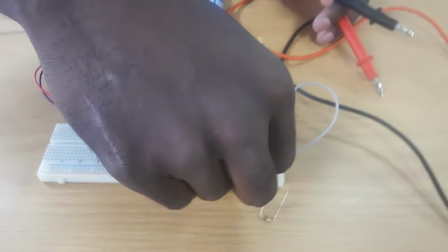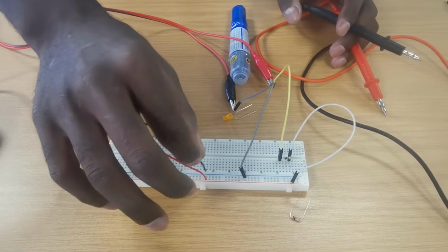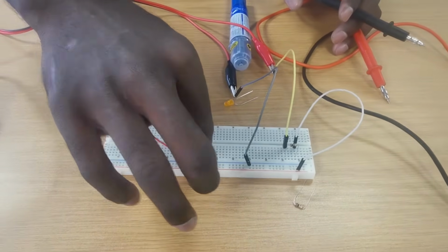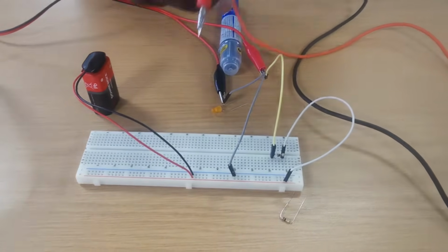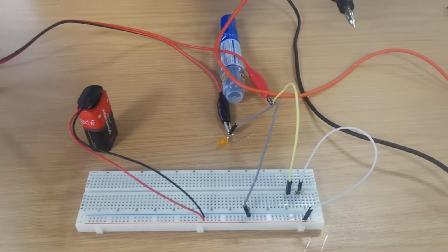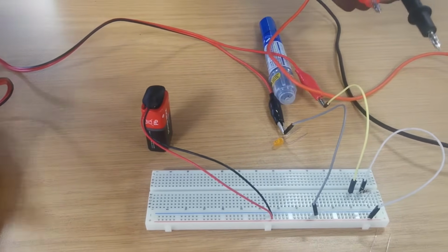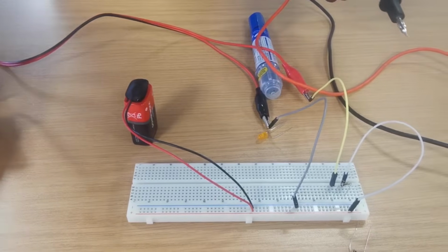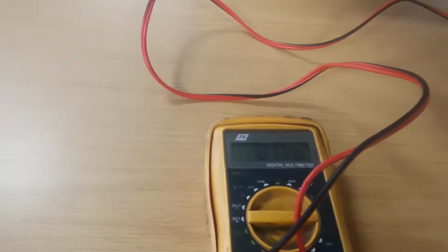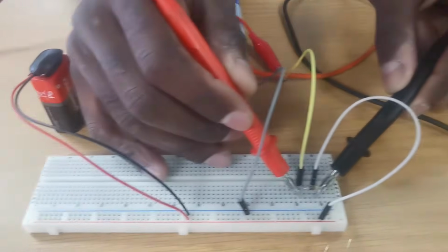Okay, and with a 100 ohm resistor, I'm expecting the current to be significantly larger, though the voltage will be the same. So I've connected my circuit back. I can see it's overloaded, that means the current is larger as we have expected. And now it's giving us a value of 80 milliamps, whilst the voltage is still the same, because the voltage